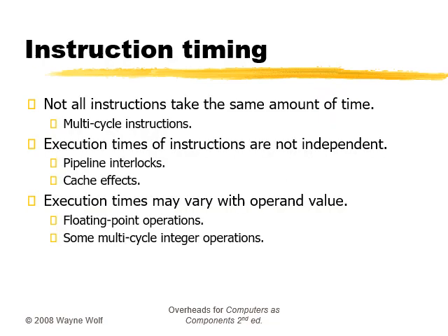In this slide we'll talk about instruction timing. Once we know the execution path of the program, we have to measure the execution time of the instructions executed along that path. The simplest estimate is to assume that every instruction takes the same number of clock cycles, which means we need to count the instructions and multiply by the per-instruction execution time to obtain the program's total execution time. However, even ignoring cache effects, this technique is simplistic for these reasons.